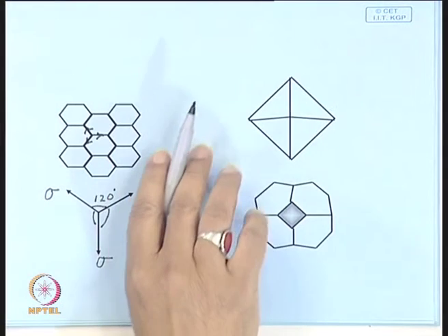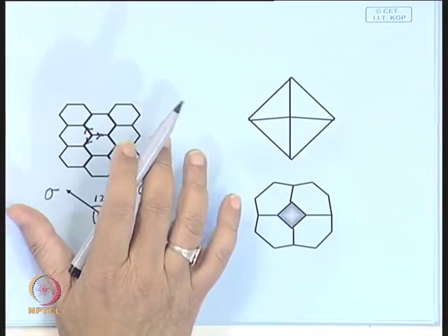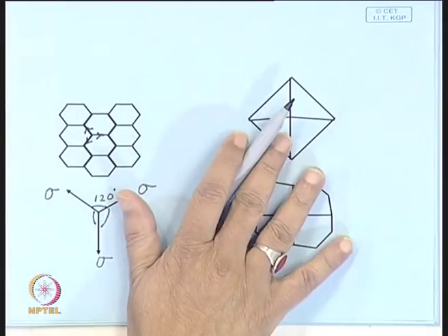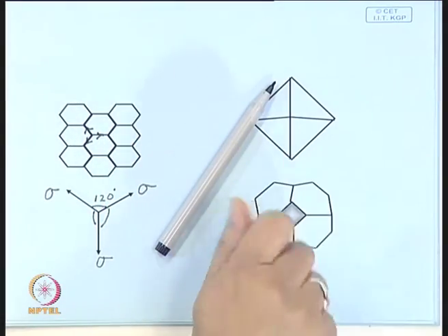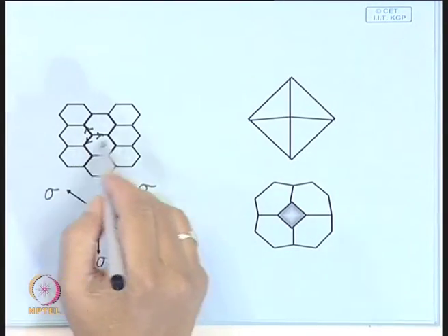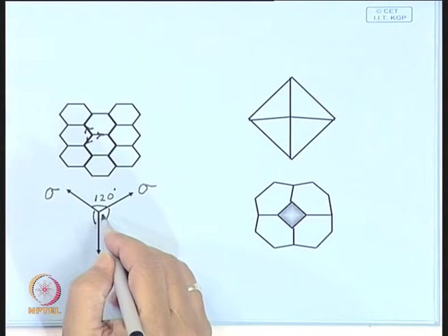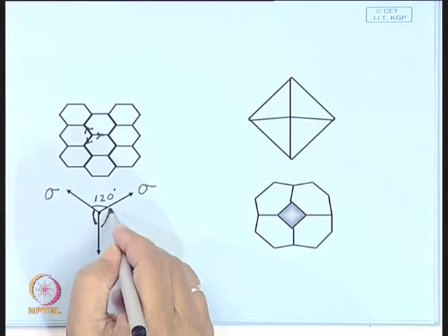So, therefore, it is not that the grain surface energy of the crystal on every surface is the same, but the difference in the surface energy with respect to the orientation, the magnitude of this difference possibly is very small. So, therefore, whenever you look at a 2D structure, the simplest experiment to do is with a soap bubble. If you take a ring, put it in soap water, take it out, you will find that the soap bubble which forms, that is a 2D structure, they all will be like regular hexagons, and it maintains this equilibrium.